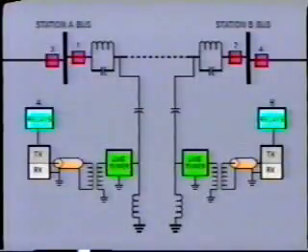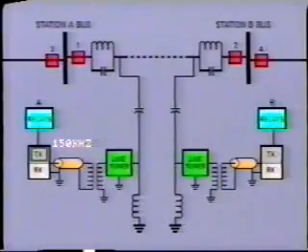First, consider this simple on-off scheme, a blocking signal for pilot relaying. When the protection relay at Station A operates, it switches on the transmitter, which is already tuned to send a signal at the desired carrier frequency, say 150 kilohertz. The signal power leaving the transmitter will be typically 10 watts, but other levels of power are also utilized.